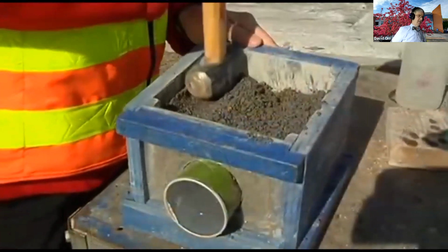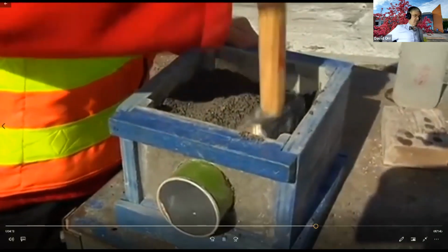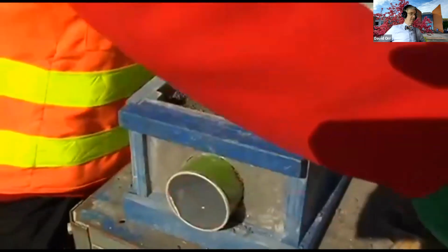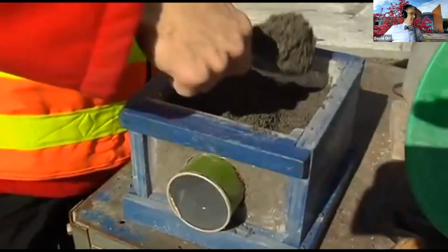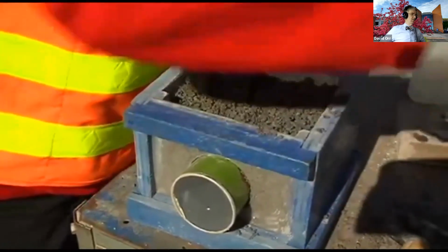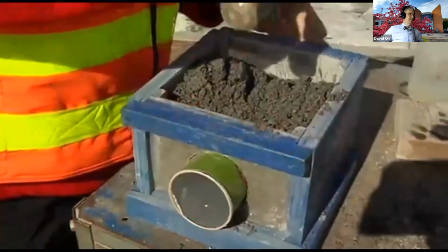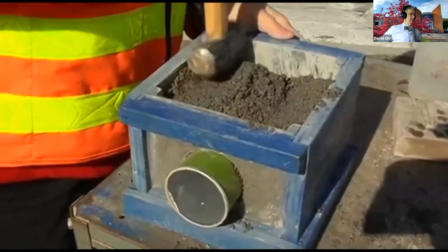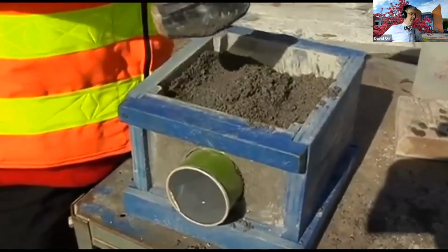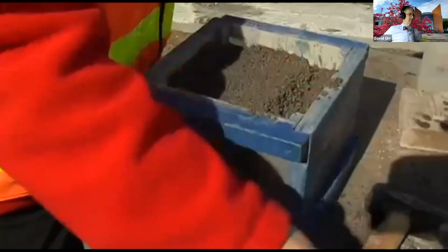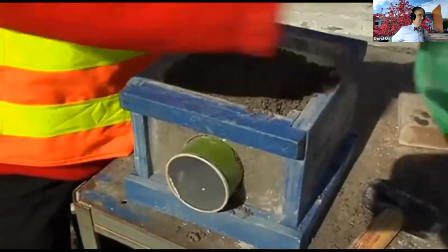When I get to the top of the pipe, I actually come up above before I compact along the top. I do that for two reasons. One, I don't want to damage the pipe by hitting it with the compactor directly. And two, by compacting across the sides up a little bit, when I do go across the top, it provides a little more lateral support, helps hold everything in place.